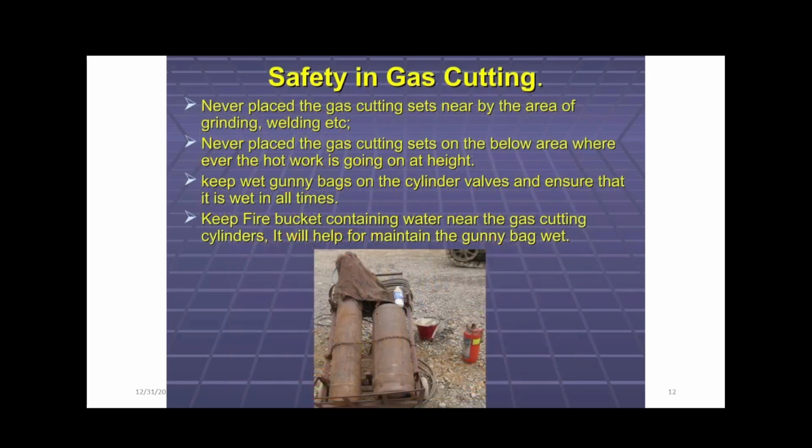Never place the gas cutting set near the area of grinding, welding, etc. Never place the gas cutting set in the area below wherever hot work is going on at height.